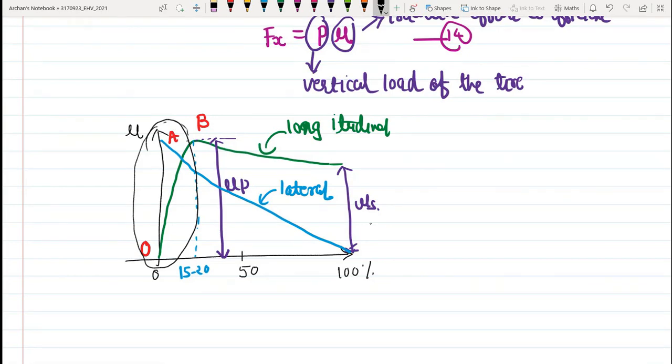The tread elements are compressed before entering the contact region, so the distance that the tire travels will be less than the distance in a free rolling tire. Because of the nearly linear elastic property of the tire, the tractive effort slip curve is almost linear, as we can see.